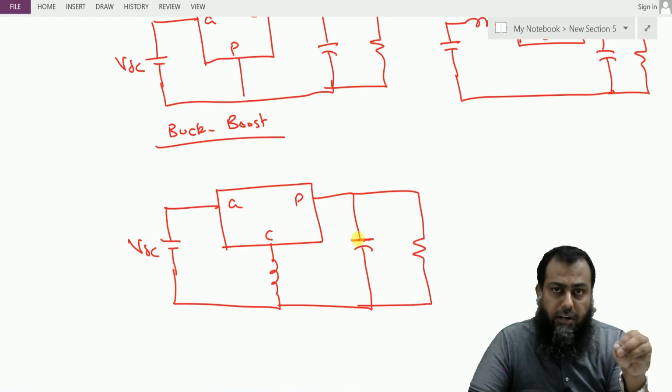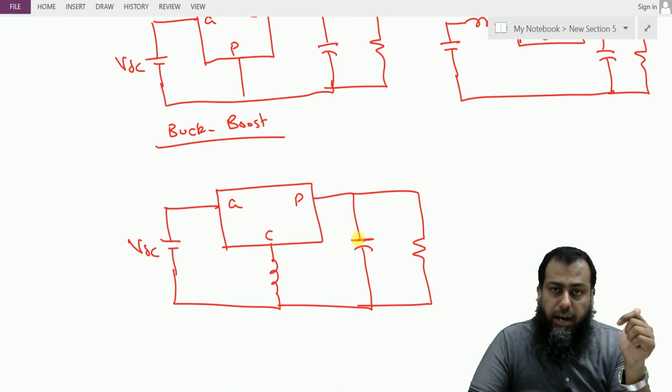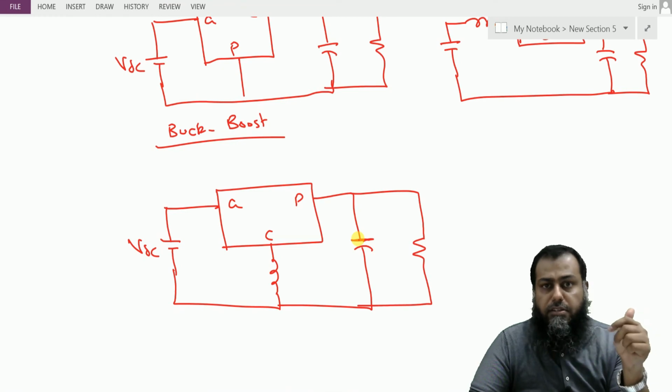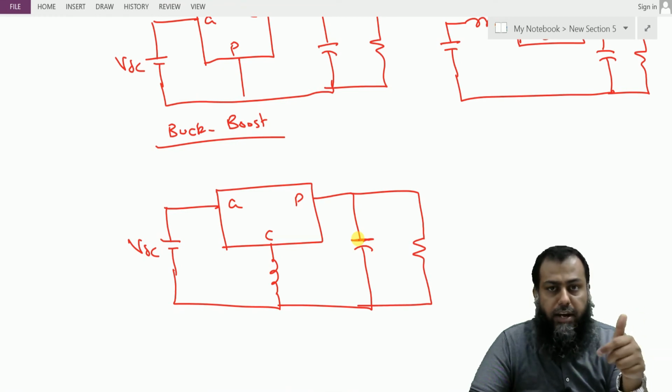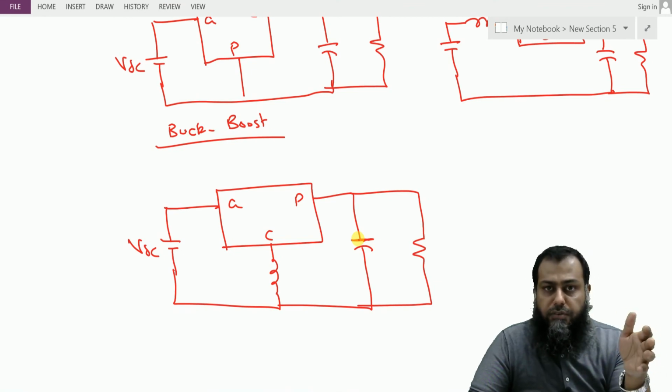And also, without using the converter switches, which are the BJTs and IGBTs, we use dependent voltage sources and dependent current sources to simulate this particular thing. Now, these two approaches of simulation can be simulated in PSpice, LTSpice, or any other Spice compatible program. But we will describe this average switching scheme using PSIM for this particular buck converter, and we will show you that whatever we are getting through a switched model can also be obtained using the average model. So let us now shift to the process of the simulation, and thereafter we will wrap up this lecture.